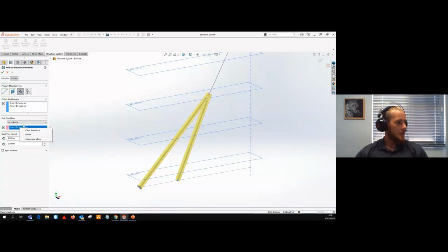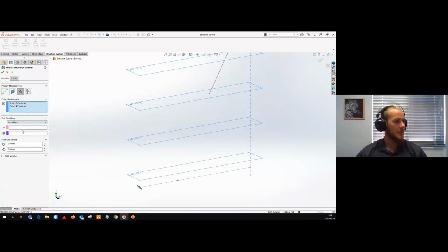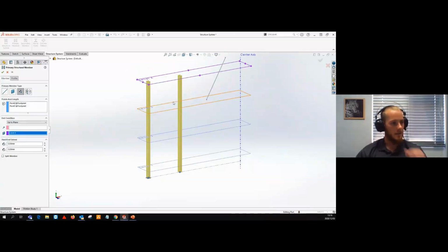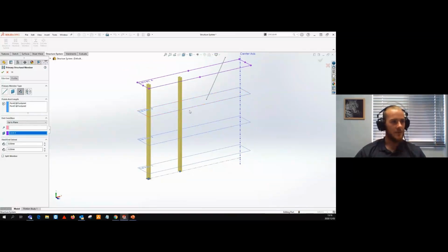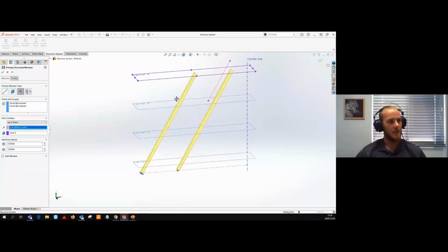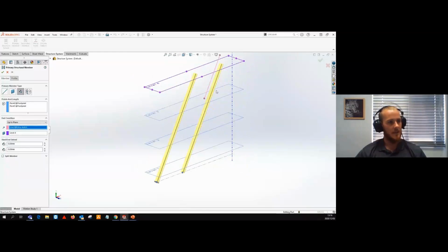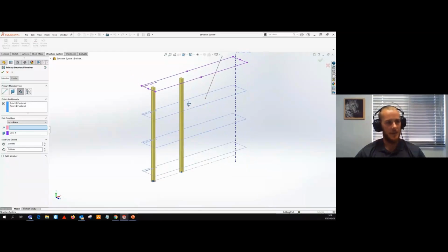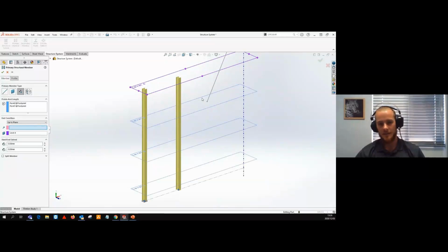So for this afternoon, we will be looking at the up to plane end condition. And this is quite lovely. It allows me to just select the plane, and you guys will notice the points are used as position, and the plane is actually used as the end reference. There are additional options here. I can, for example, change the direction of the extrude, if you can put it that way. You guys will notice I'm just selecting this line. This can obviously be anything like an angled plane or even an axis resting at a specific angle.